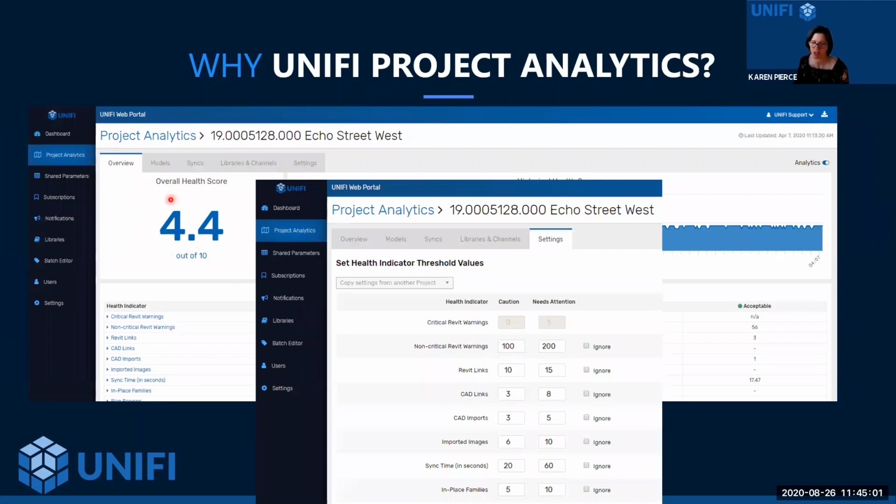These health scores also help you gain visibility into the actual health of the particular model you have here. So while we will lock down the critical Revit warnings, because for critical, you shouldn't have any in there, I can set my thresholds for non-critical warnings. When does it maybe start to slow down my model? And then I'll be concerned with it and be able to analyze it as it occurs. Revit links, CAD links, imports, imported images, sync time, in-place families, we're looking at all of that to effectively come up with this health score for you.